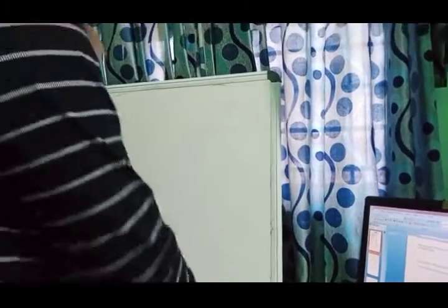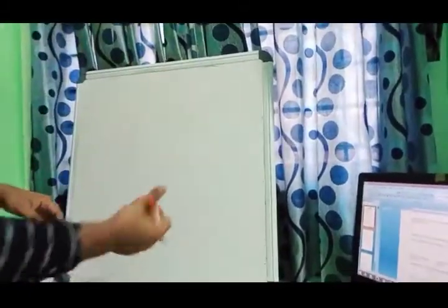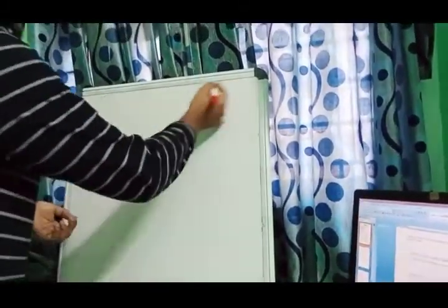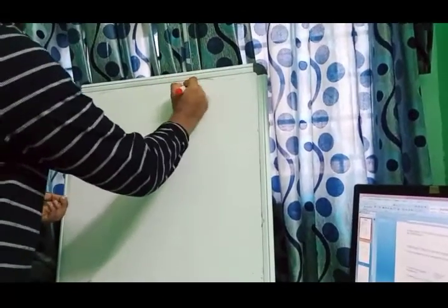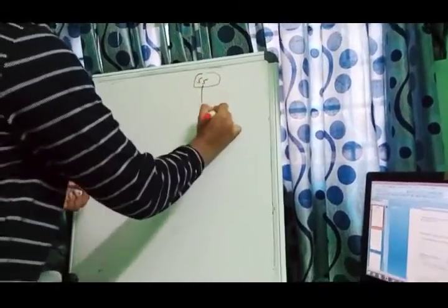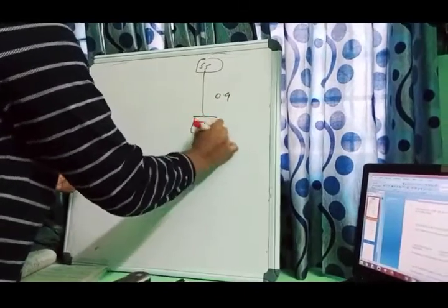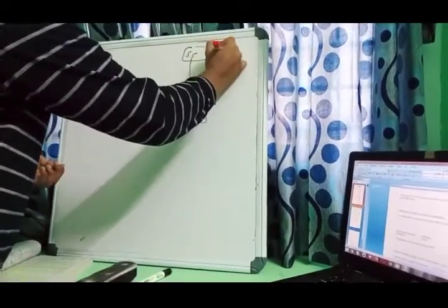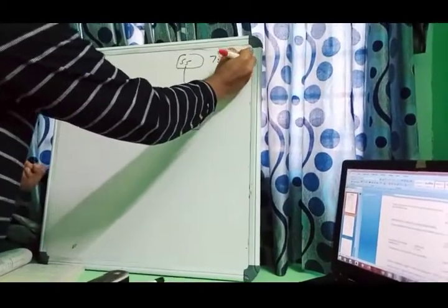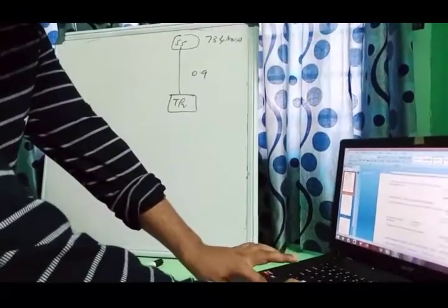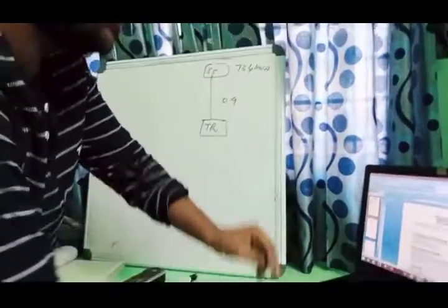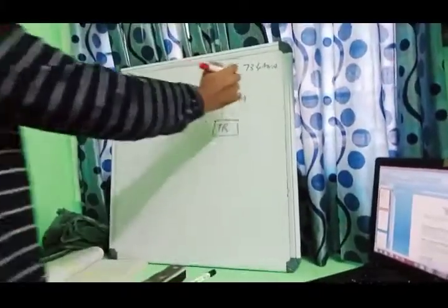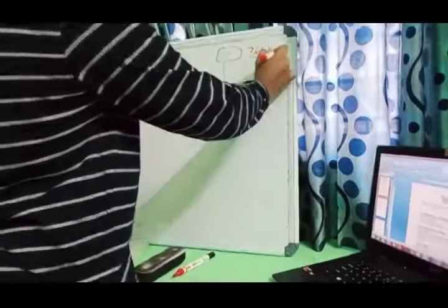We will be discussing this equation on the basis of a real life example of an industry which is taking its supply from a nearby substation at a point. The substation is located 0.9 kilometers away from the industry's transformer. The substation has a pre-calculated fault level of 93.4 MVA. Every substation will already have a pre-calculated fault level.